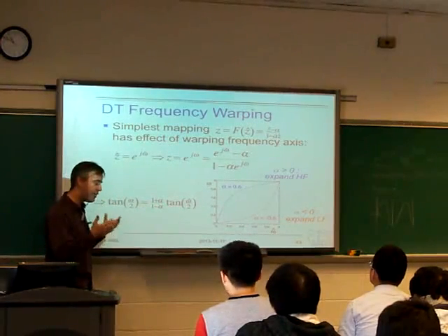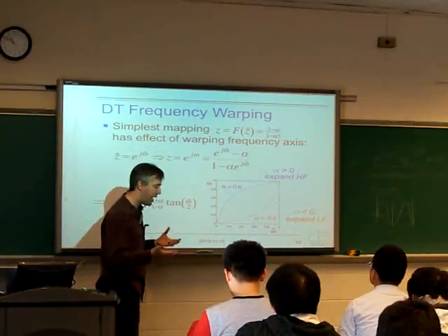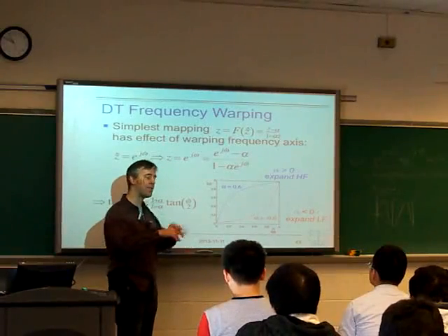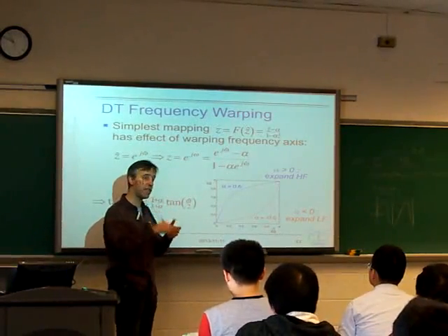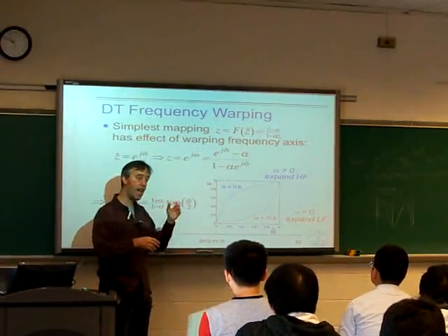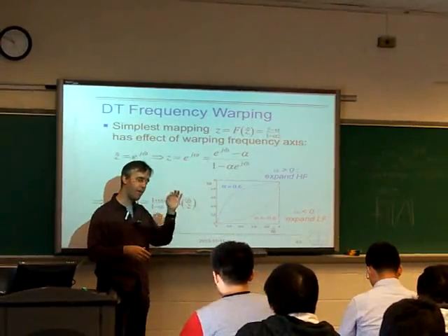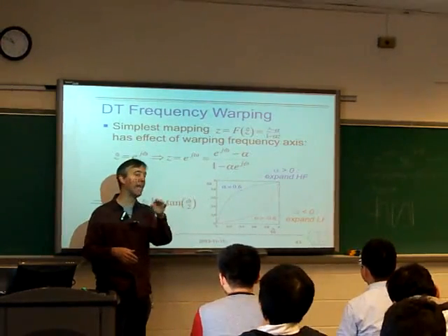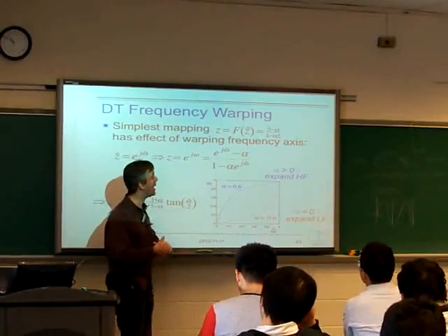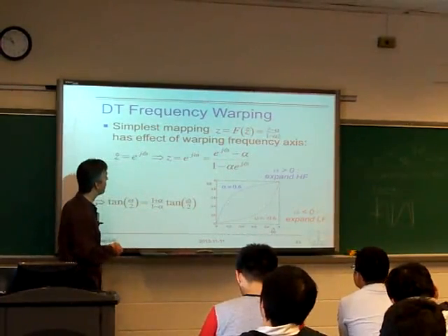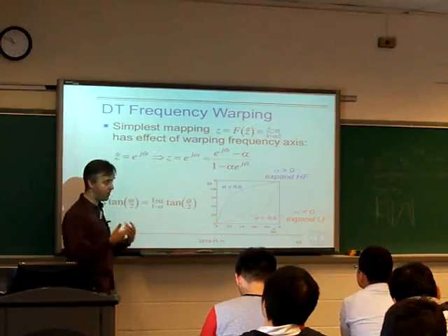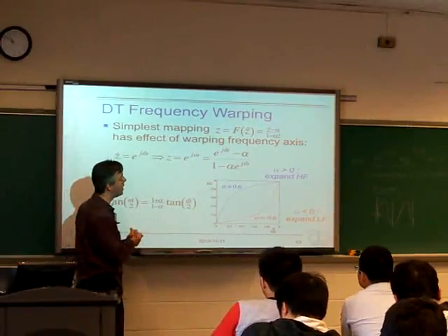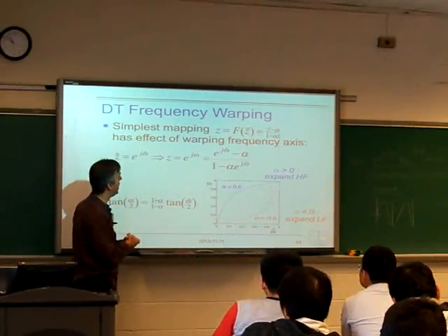Of course, as with the bilinear transform, the key point about this transformation is, well, where do those frequency points line up? We've mapped the frequency axis to the frequency axis, in this case the unit circle to the unit circle. But if I have a particular gain at some frequency in my original filter, for which frequency does that gain land up in my mapped filter? And so it depends on the phase of the all-pass filter that you're using to replace the delays.